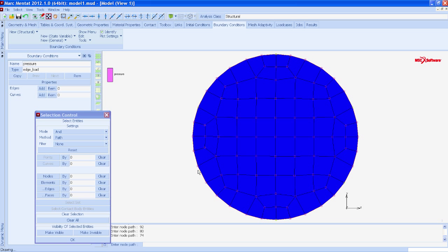and once we select, I'm going to end with the very first node we picked. At this point it has selected 32 edges, everything on the outside. This is definitely a quicker way rather than box picking or even polygon picking. But there's still one drawback in that you have to pick a bunch of nodes on the boundary. And sometimes if you're not careful, especially depending on the curvature, you can pick some edges that you don't want.